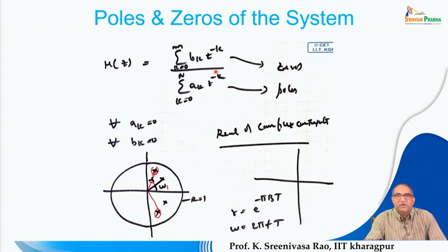If you analyze the poles of a transfer function and solve the factors, as I mentioned, if the coefficients are real, you will get either real roots or complex roots, and if the roots are complex, they appear as complex conjugates. That means you will always get a pair of roots, because ultimately you have to get real coefficients. From real coefficients you get a real root, or otherwise, if the roots are complex, then to get real coefficients back, these complex roots happen to be paired, and they are complex conjugates.